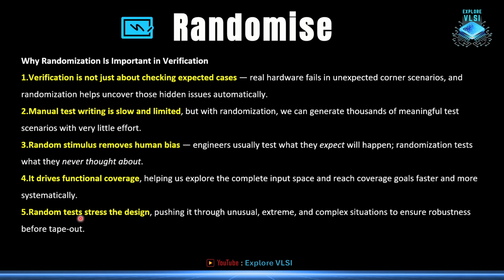And random tests stress the design. Yes, pushing the DUT through unusual cases, extreme situations, and complex situations as well, to ensure robustness before the tape out. Once the tape out is done, you can't test the DUT through simulation again.